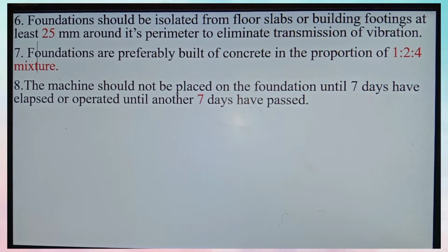Rather, we have to wait until 7 days have elapsed before operating, or until another 7 days have passed. So meaning to say, we need to place the machine on the foundation only after 7 days have elapsed, just to make sure that the concrete mixture has hardened and cured properly. So at least 7 days have passed just to attain curing of the concrete mixtures.